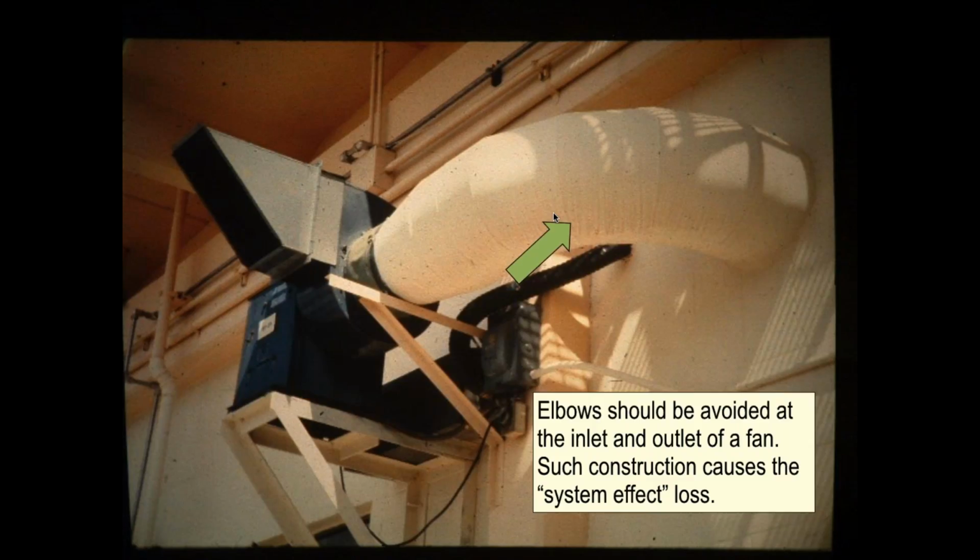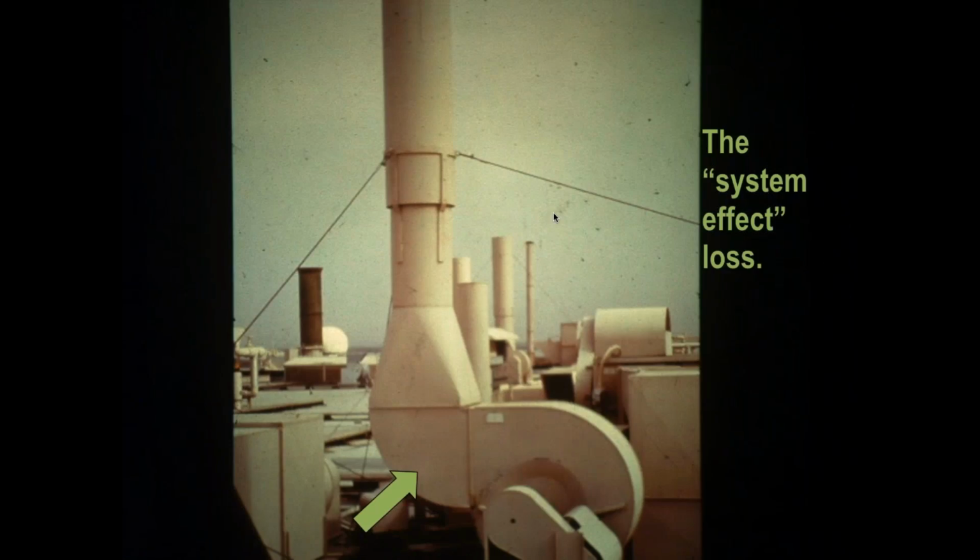When you drive your car, the wheels don't have the same revolutions per minute as the engine. That's why you have a transmission. Exactly. The gearing can make it go up or down. You have a lot of flexibility with pulleys and gears, right? The only problem is you have limited flexibility, because if you have a slow motor and you have to gear it way up, or a fast motor you have to gear way down, then you put all sorts of stresses on the gears. It may not work all that well.